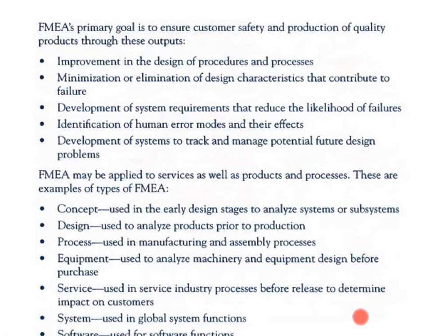So if you can engineer out bad design, that can also go into where people might get injured from an accident, confined spaces, falls, things like that. We might be able to reduce that. An example that I give, at least from fall protection, is that most people that have to work on roofs, most parapets are built 36 inches high, right? Well, the Cal OSHA requirement for guardrails is 42 inches.